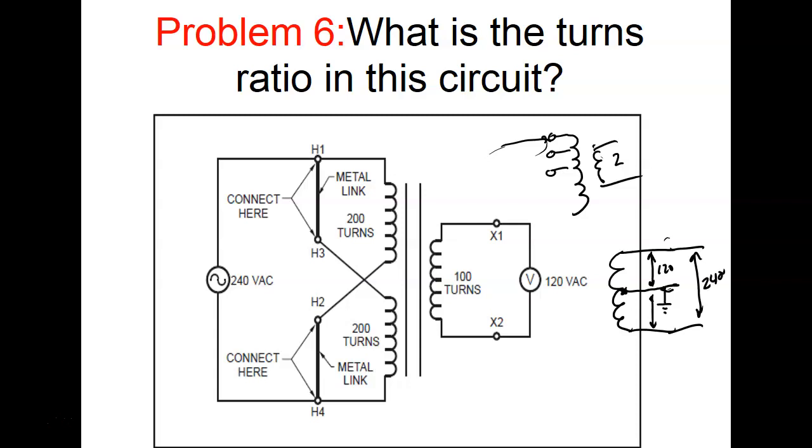And then Tuesday or Thursday, we'll do our first hands-on lab. The first thing we're going to do is measure voltage inside the disconnect. We're going to hook up a transformer and wire it for low voltage. We'll wire it for divide by 4 to start off with, then divide by 2. We're going to measure the outputs to see the actual division ratios. Then we'll end by hooking it back up to divide by 4, because that's what we're going to use the rest of the semester.